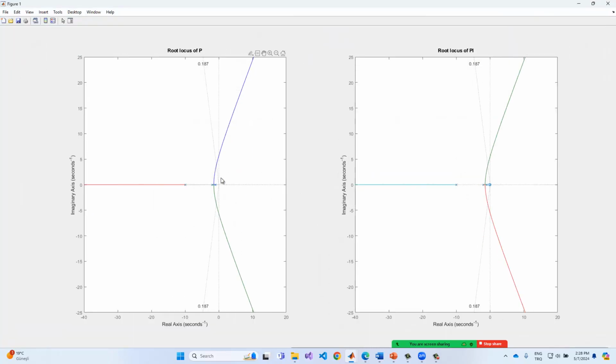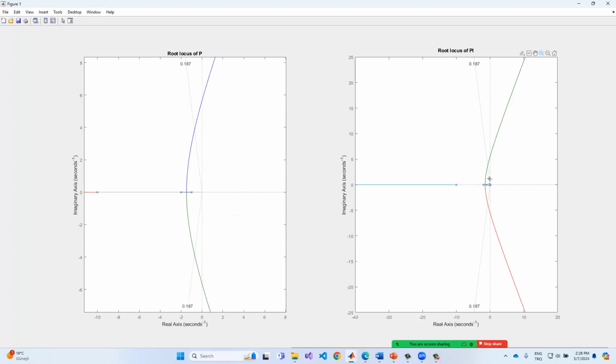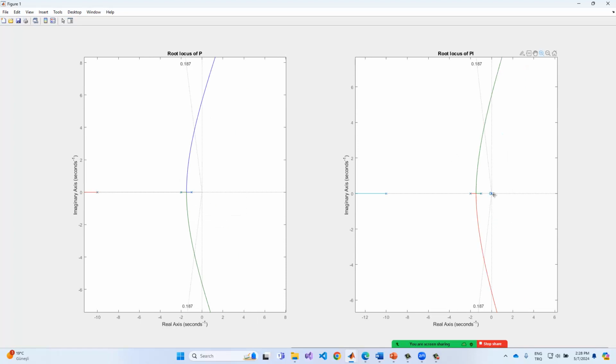we have the two root locus plots, but see that these two root locus plots are different from each other, right? This root locus has this shape, and this has this one. We have a 1 zero and the integral term, which cancel each other in here, but the root locus of PI is changed relative to the P one. See that? And so how can we affect these results?